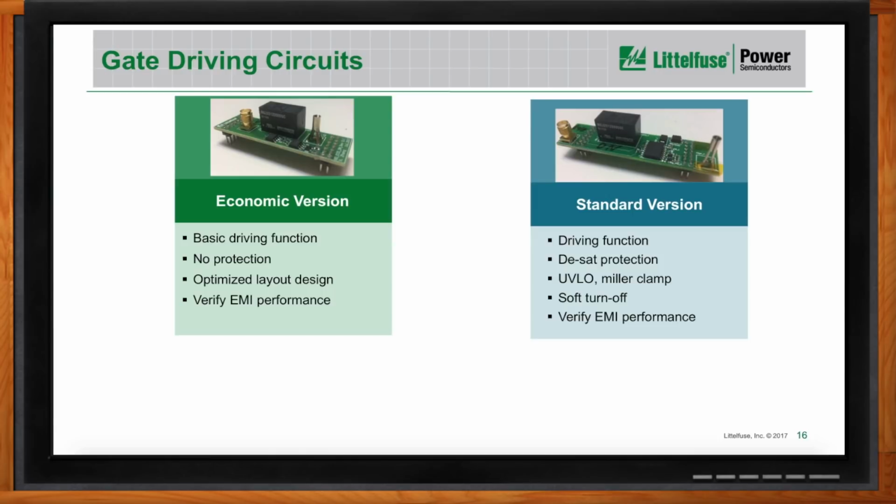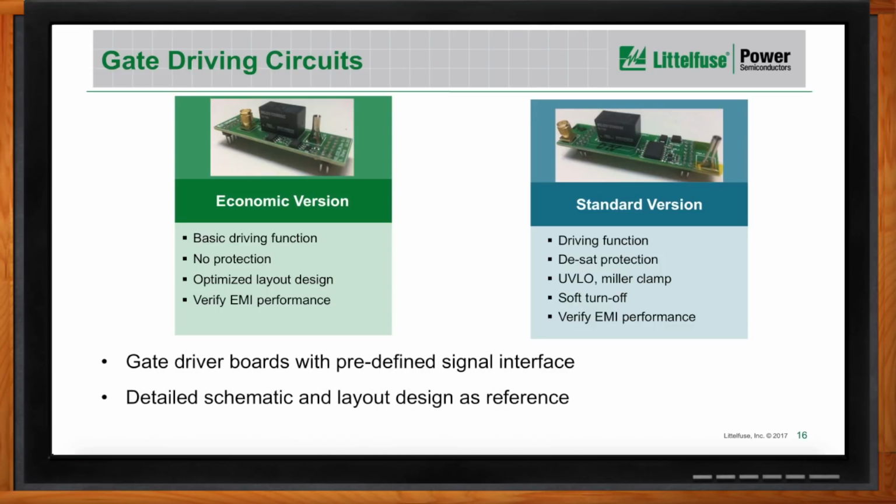And we also provide the standard version gate driver, for which we predefined all the protection features, including the DCP protection, under voltage lockout protection, active Miller clamping protection, and also the soft turn off during the protection action. And for this gate driver board, we will have a predefined signal interface, and also on our website, you will find all the detailed schematic and the layout design as a reference for our customers.